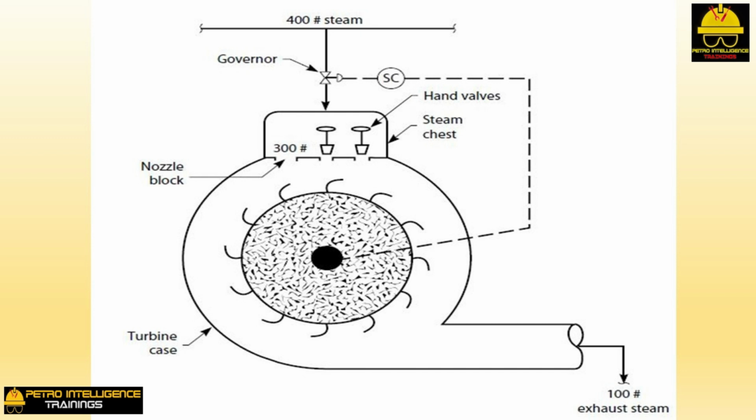The velocity of the steam striking the buckets will also increase. The turbine wheel will now come back up to its set point. The net effect of this exercise will be to save not 20% of the motive steam, but 10%. The 20% reduction in nozzle area is partially offset by the opening of the governor valve.